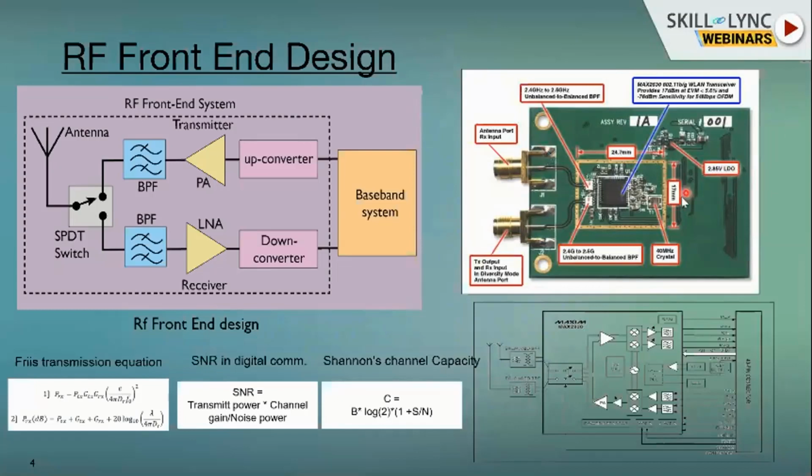Here you could see all of these connected. They are connected to the antenna, and it goes to a kind of filter, which segregates the message signal. Then it goes to the processor unit. That's how it looks. You can see it has an LNA, then it goes to the local oscillator, which will mix with the RF frequency, then segregate into the IF frequency. From the IF frequency, it goes further to your signal system. So this is how the receiver is working.